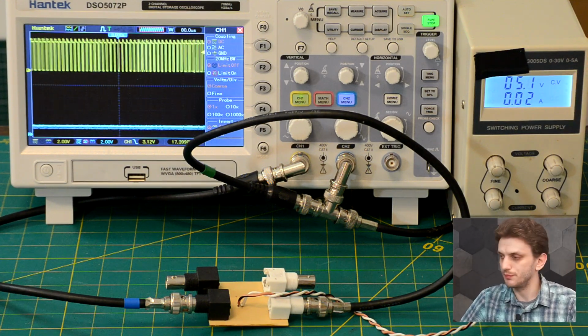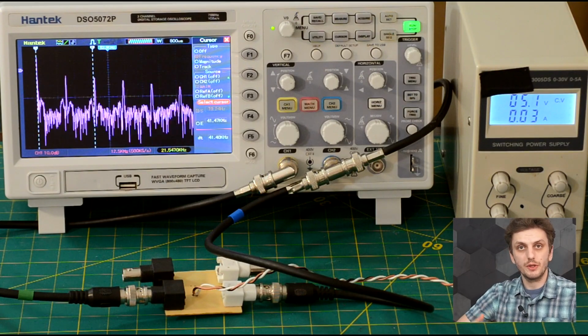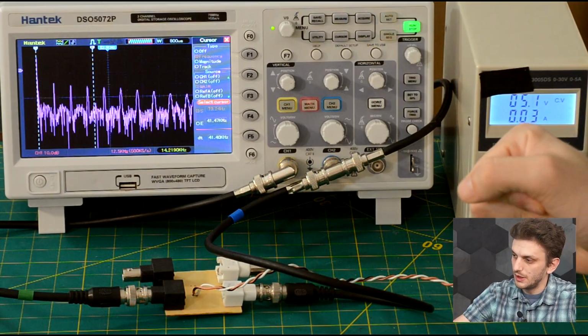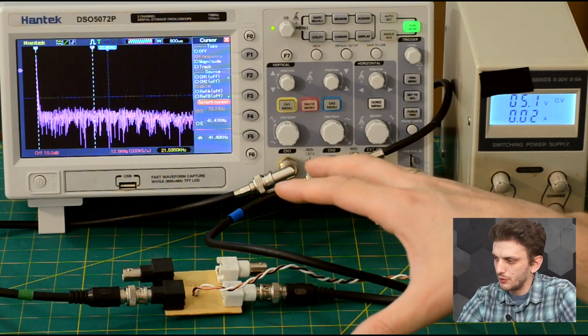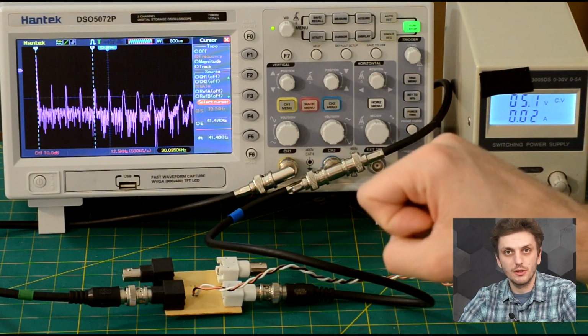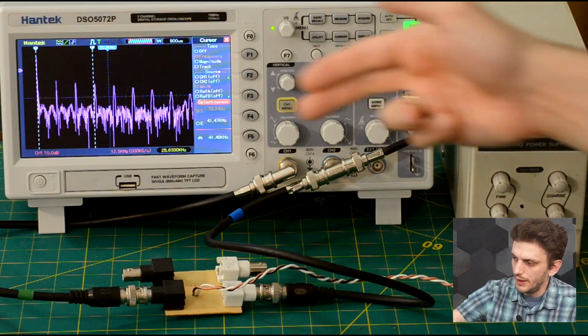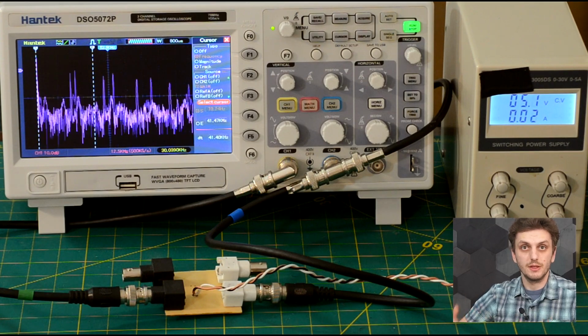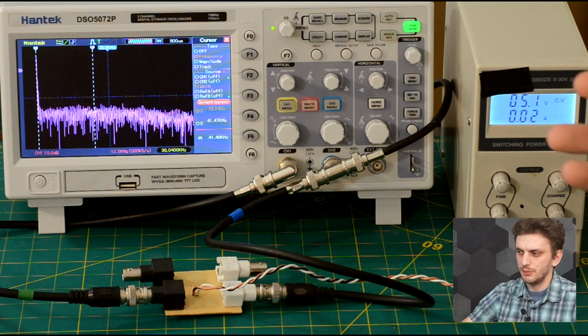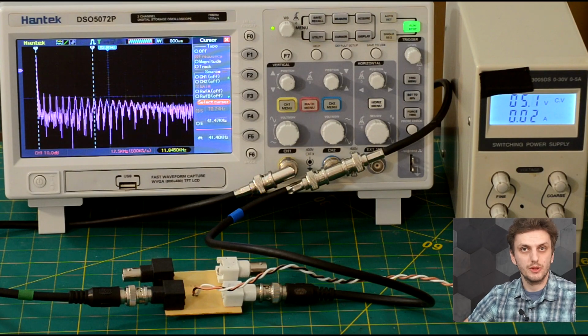Because of the large variation in current that can be achieved, we have a large variation in frequency. Now we can also see the frequency variation in an FFT spectrum. So what we can see here is our fundamental frequency varying up to about 73 kilohertz. And at the same time we can also see all of the harmonics varying in sync with it. So this is the typical spectrum you would get from a square wave.